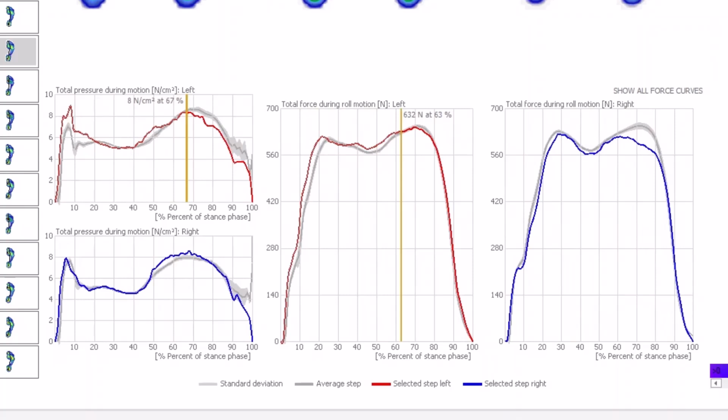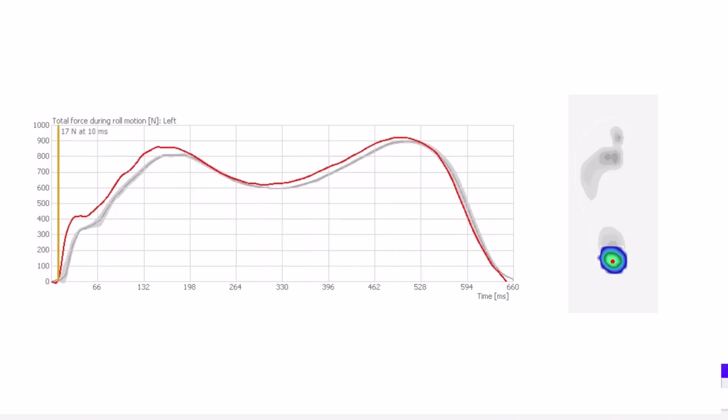The gait phases belonging to the stance phase can be read relatively easily from a force curve. So the curve starts with a small tick representing the initial contact. Since the actual load transfer does not begin until after this point, the deflection initially decreases again a little. This is due to the initiation of the physiological heel eversion and the soft heel cushion that initially transmits the force. From this short moment on, however, the force curve begins to rise analogously to the load transfer.